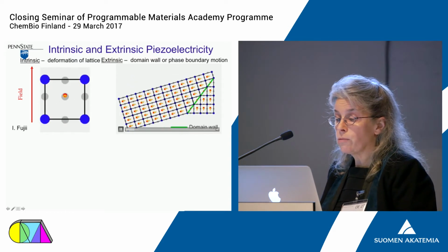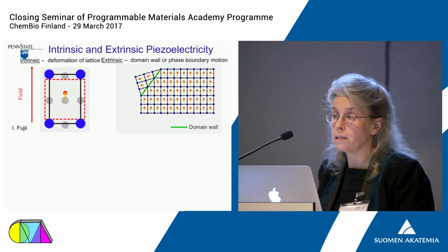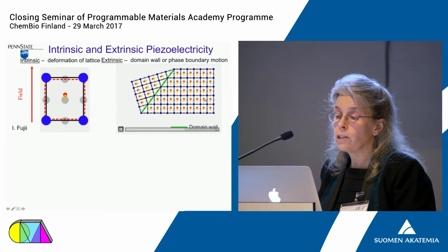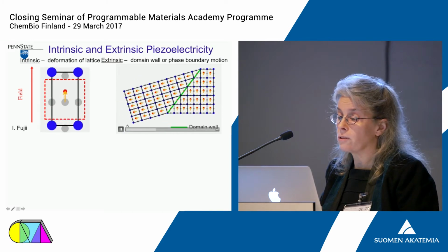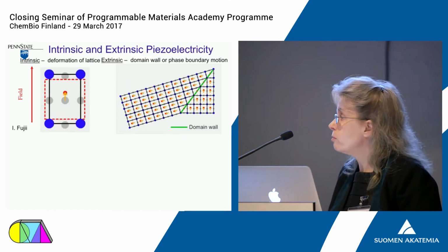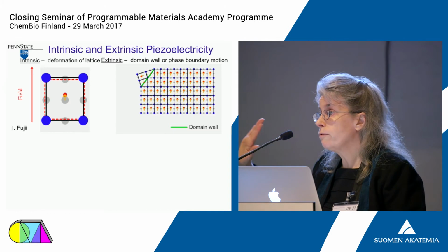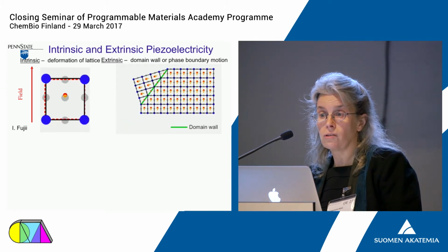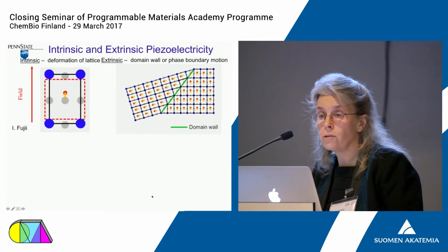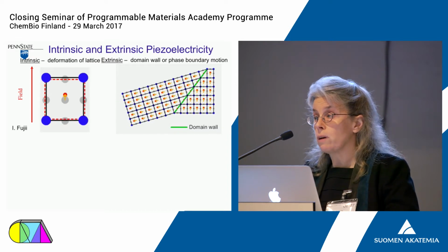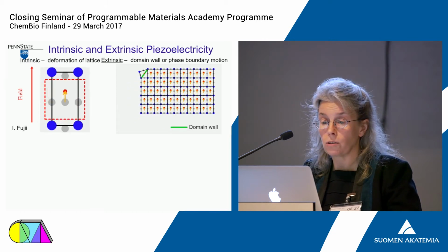There's a second major contribution associated with the fact that these materials are all ferroelectric, so that they have more than one possible orientation for the polarization. So I show here the case where I have polarization in the up direction and polarization directed off to the left. And you can see that those two ferroelectric domains have different shapes, different distortions. And as I move the domain wall, that's shown in green, through the solid, there is an accompanying shape change that's associated with that as well. And those two mechanisms are the primary mechanisms by which we develop functional, large piezoelectric responses in materials.